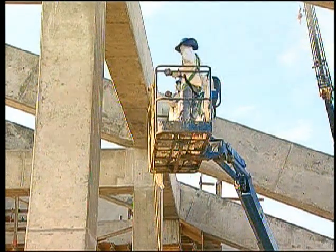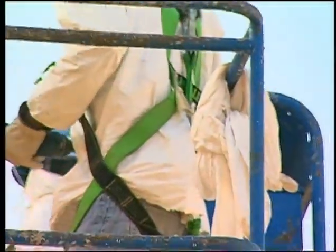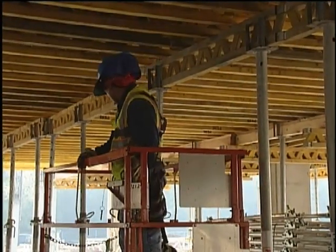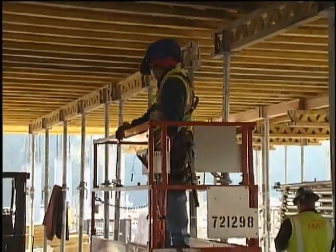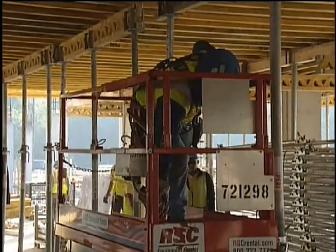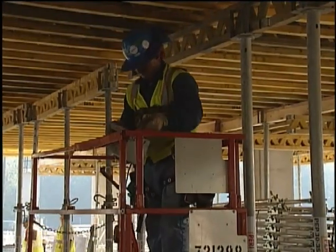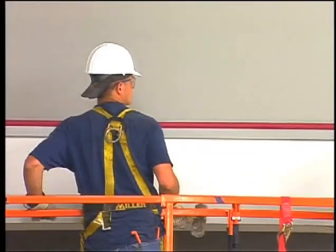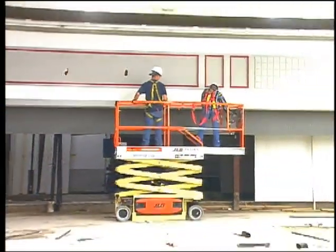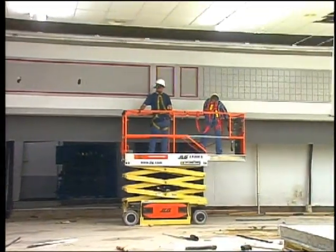Fall protection is required for all personnel that perform work on a lift if they are going to be elevated to a height of 10 feet above a lower level. If the lift is used according to manufacturer's guidelines and all safety precautions are followed, the chance of a fall is minimized. All scissor lifts require fall protection. Guardrails that are properly designed, maintained, and meet OSHA guardrail requirements are sufficient fall protection. If the guardrail does not meet OSHA standards, or if an employee leaves the safety of the work platform, then a personal fall arrest system utilizing a full body harness is required.